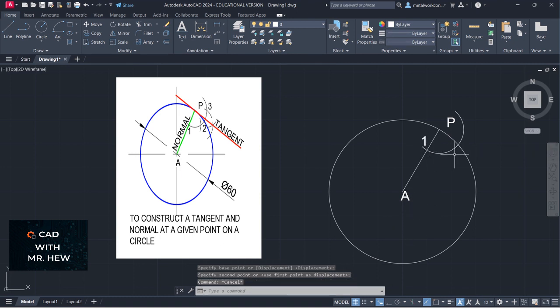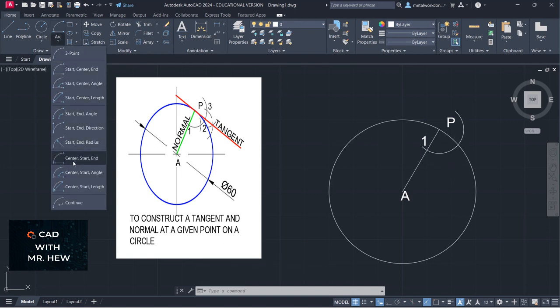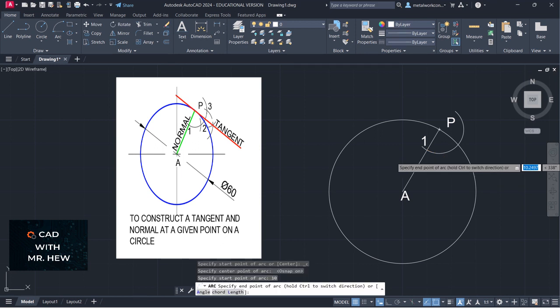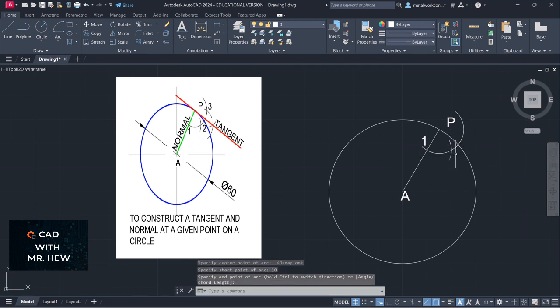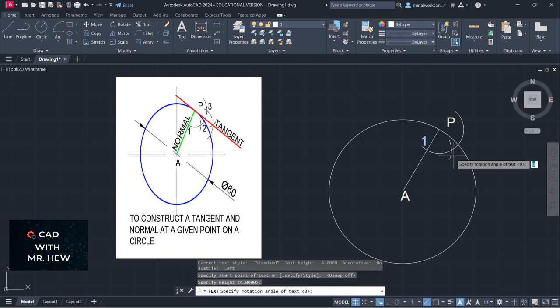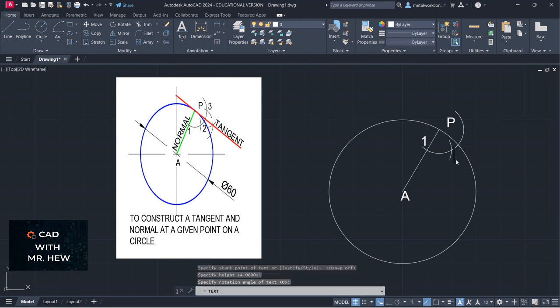At 1, we're going to mark an arc to intersect the semicircle that was just drawn a while ago with the same radius as the previous arc. So center at 1, I need to turn on object snap. Center at 1, radius 10, mark an arc. All right, that will be 2. So let me label it for you, 2. Again, you don't need to label it. I'm just labeling it so you can follow in the class, okay? So this point would be 2. So I go, height is 4, rotational angle is 0, and this point is 2.